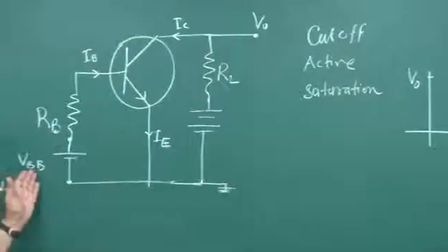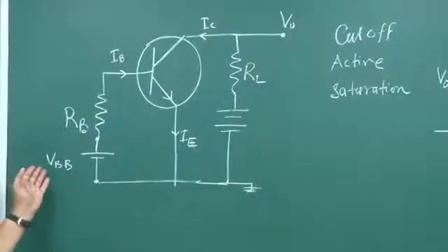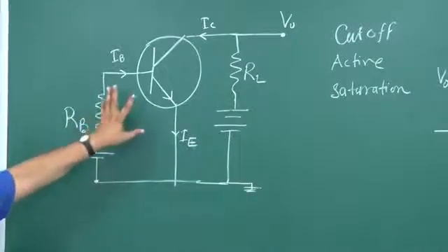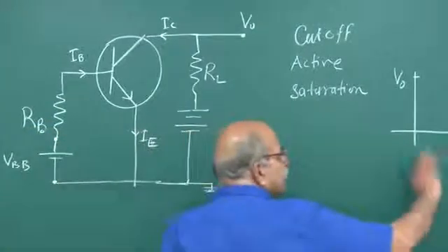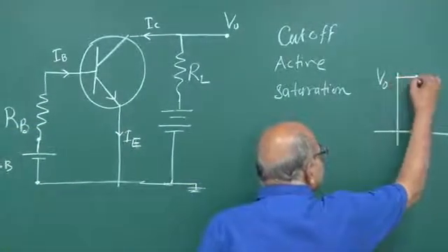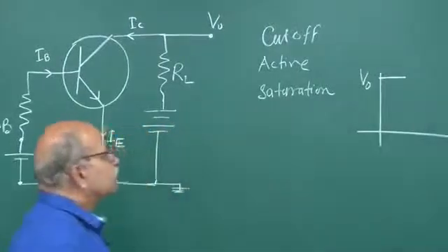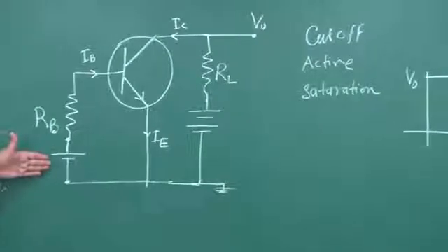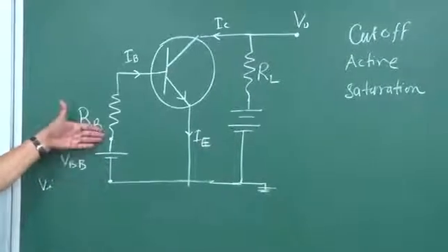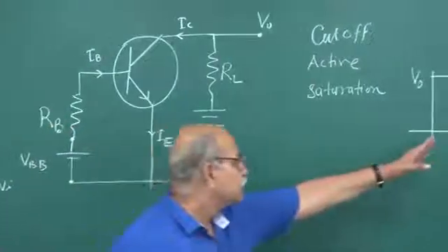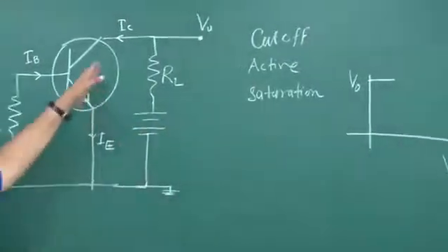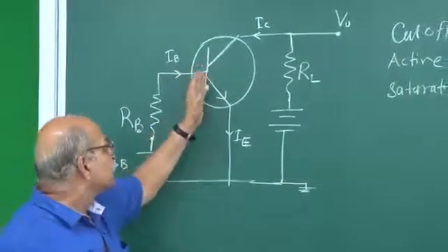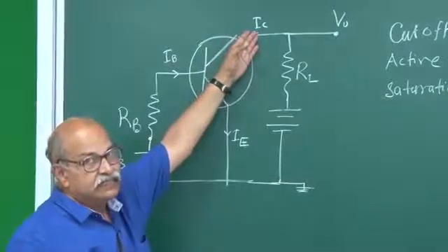And if you increase it slightly little bit, it is still not forward biased with sufficient strength, and it remains in cutoff region. So, you increase this VI, and initially this will remain at V0. So, that is the cutoff region, and then starts active region, in which you have a biasing voltage which is say more than this, and then electron injection starts, and those electrons are being drawn here, IC appears.